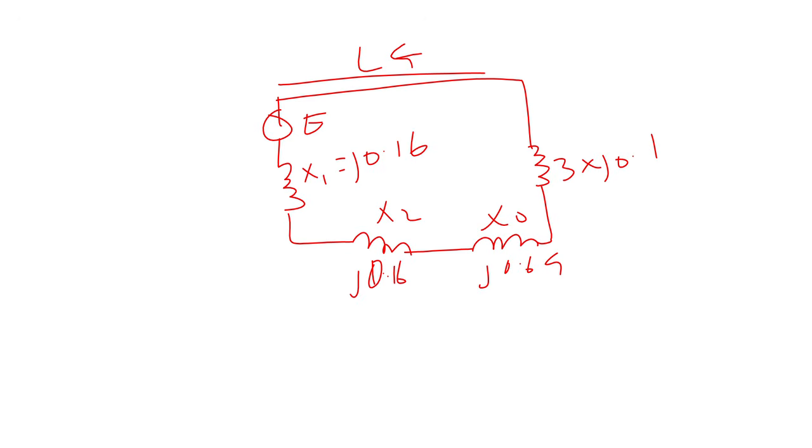So when it's a line to ground fault, the same calculation goes on, just that the arrangement of x1, x2, x0 is what is going to change. You realize that for the line to line to ground we put them in parallel, but this is in series. So here too, we find our I0, and I0 will end up being E1 divided by X1 plus X2 plus X0 plus 3 times XF, right?